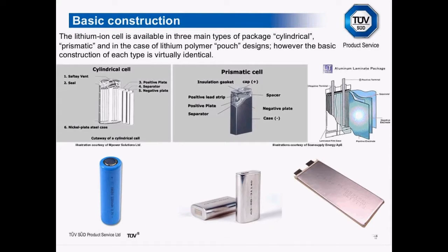The lithium-ion cell that is used in the actual battery pack can be found in three main types. The first type is the cylindrical, such as the 18650, which refers to the size of the cell and was the first lithium-ion cell to market. The prismatic was next to market, followed by the pouch cell, also known as the laminated cell. This cell has made a big impact in the cell industry due to the fact that the closure is flexible and is considerably slimmer and lighter than conventional prismatic and cylindrical cells.